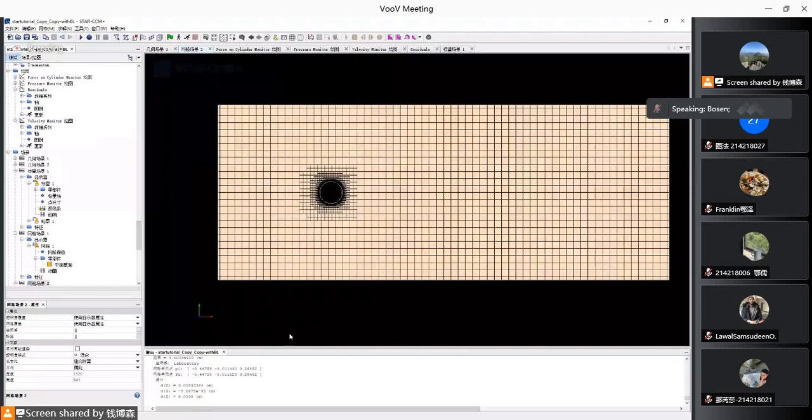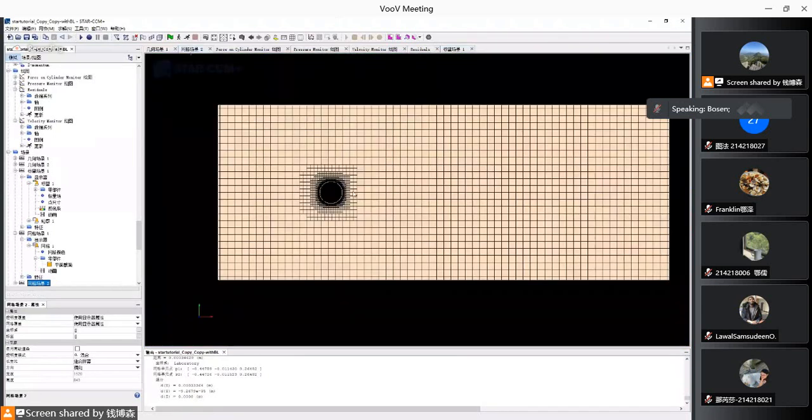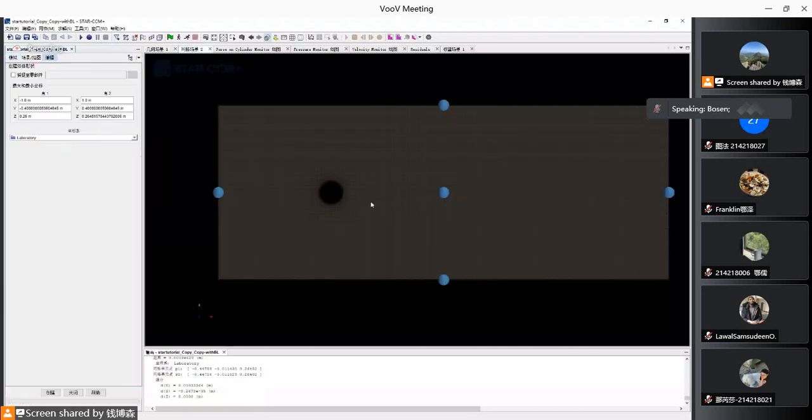Okay, so that's one important thing I would like to mention. The other important thing, we have seen that the result now doesn't look like this because we have finer boundary layer. However, the grid resolution in here is very, very poor. So what do we do? We want to apply local refinements in here. There's the body shape in here. We apply a new shape.